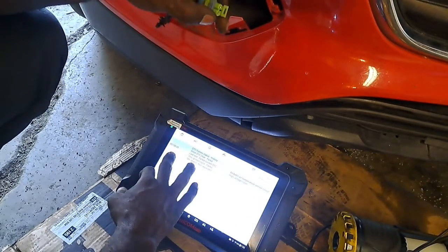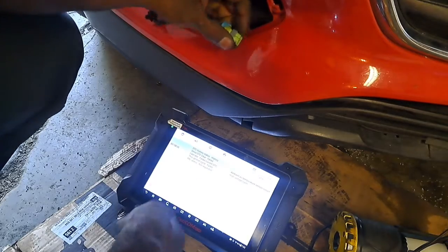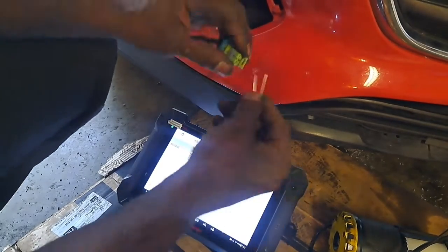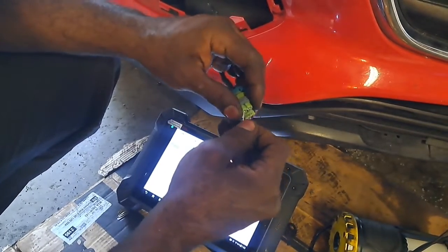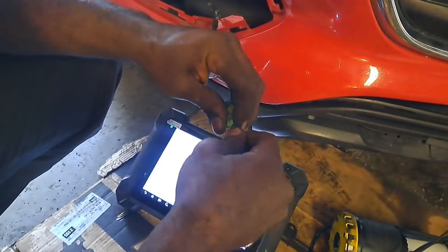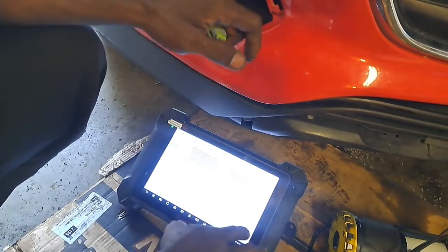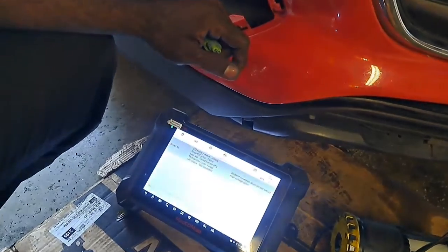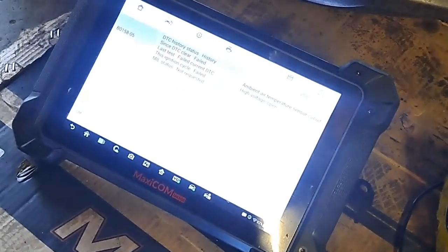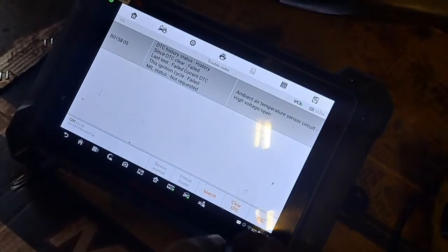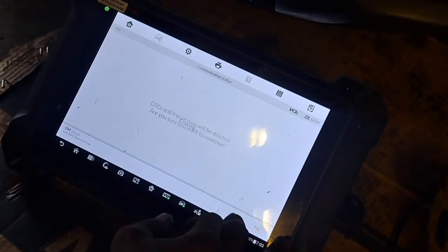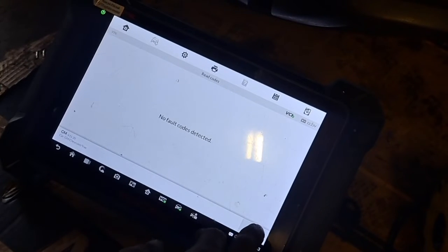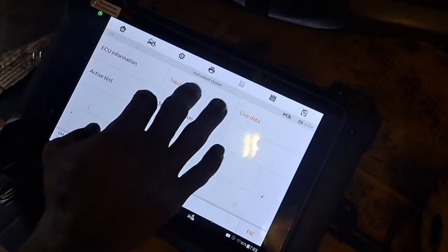So when I had a 158-02 before, when I shorted the pins, let me show you that. So I'm gonna short them. Leaving it unplugged gave us a high code. Shorting it, let's see if it'll crop up. Shorting it will give us the 158-02 versus the -05.